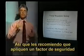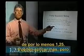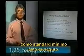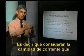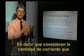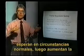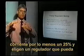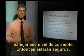So I recommend that you apply a safety factor of at least 1.25. You can apply more if you want, but I think as a minimum standard, this is safe. In other words, you look at the amount of current that you would expect under normal circumstances, and then increase your current by at least 25%, and choose a regulator that can handle that level of current.